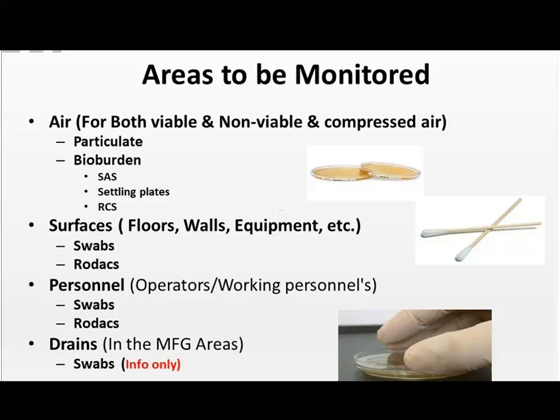If you have a filling machine and you want to monitor the filler spout that is actually pushing the liquid into, say, a bottle, then the swab is very good to use because it's not a flat surface. Swabs are used for difficult locations, maybe to get down into a tank, the top of a tank, the bottom of a tank, or the outlet port of a tank.